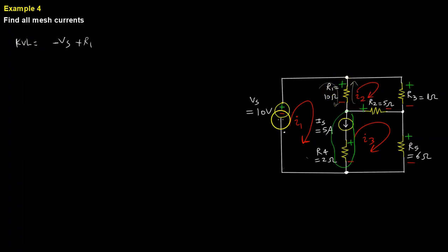The reason we do I1 minus I2 and not the other way around is that the passive sign convention tells us the current must flow from positive to negative, and the only way that can happen is if the assumption of I1 being greater than I2 is true. We're going to assume that, and if it is incorrect, the mathematics will take care of it.